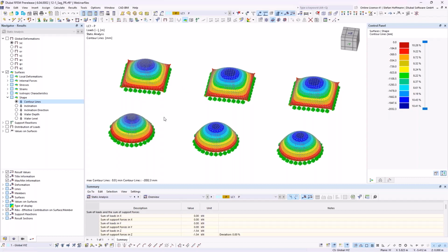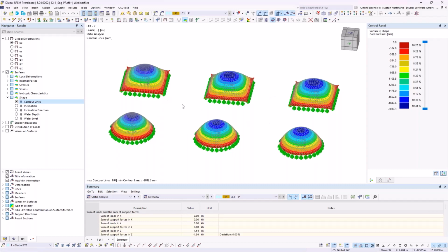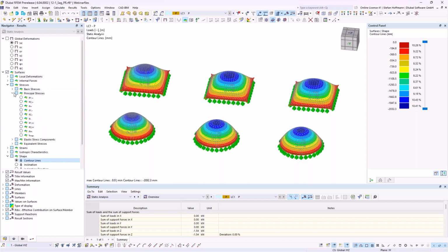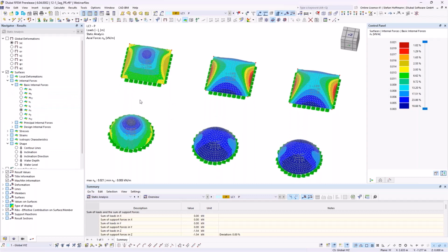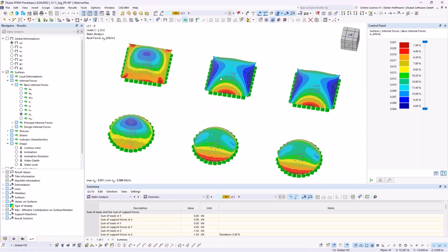We can see on the left and on the right that it's most likely a similar shape, or, well, you can see that we have some bigger circles on the standard method. But now the easiest way to check is to have a look at the internal forces of the surface. So let's check for X and Y. This is the ratio the program will find for our pre-stress we will put inside.